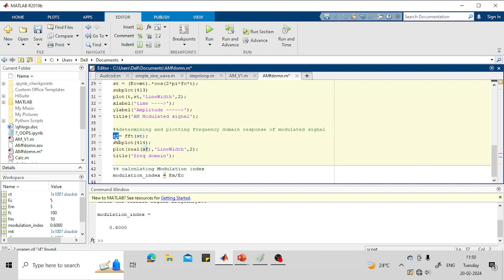In this frequency domain signal, we are having amplitude and also angle in consideration, because it's a complex plot. S of f, which is a frequency domain plot, is a complex number plot. Fine. So S of f is the frequency domain content for S of t.